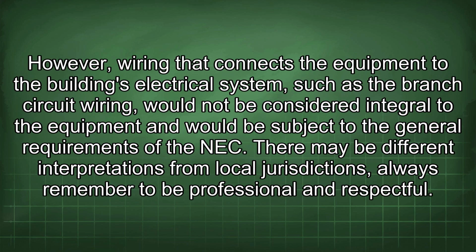However, wiring that connects the equipment to the building's electrical system, such as the branch circuit wiring, would not be considered integral to the equipment and would be subject to the general requirements of the NEC. There may be different interpretations from local jurisdictions. Always remember to be professional and respectful.